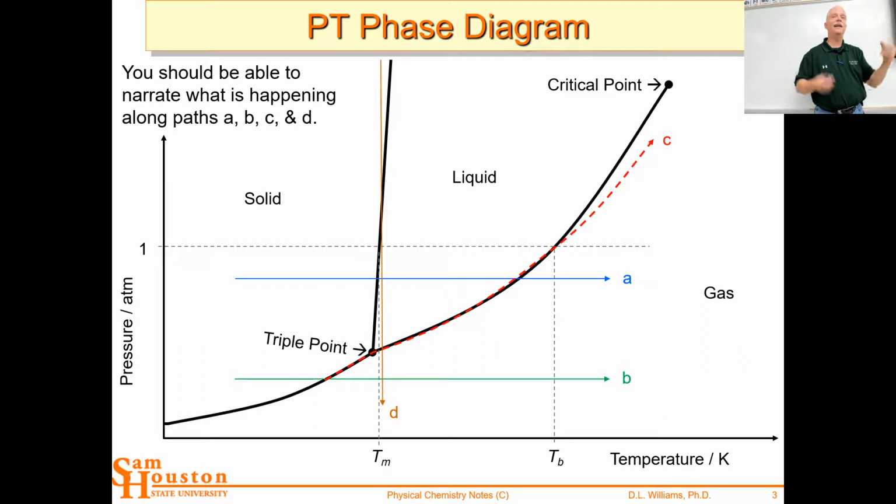Do we ever do that? Yes, we're doing that in my lab now. I bought a little vacuum chamber, and we're doing a certain type of cleaning called vacuum cycle nucleation. So we're sitting at liquid water, and we have our little sample under the liquid water, hooked to a vacuum pump, and we turn on the vacuum, and the pressure drops. Eventually, it boils, at the vapor pressure of that water at that temperature.